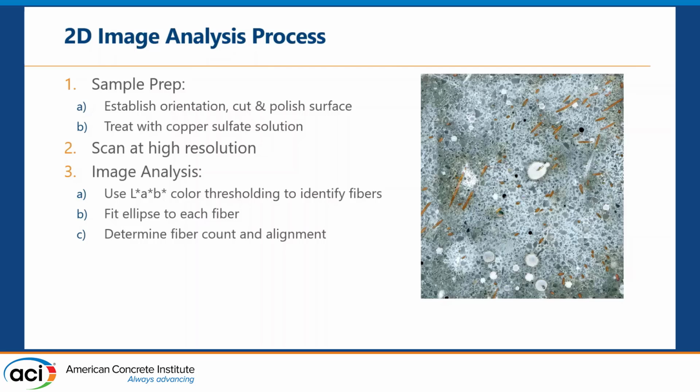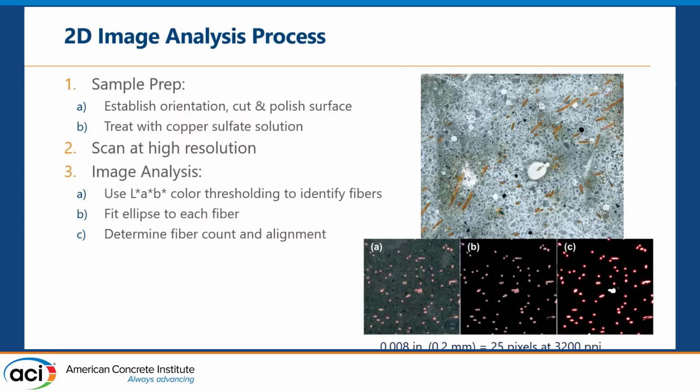We scan the surface at high resolution, and then we developed a MATLAB code that can analyze the image and can identify fibers based on the colors. We fit an ellipse on each fiber, and then we determine the fiber numbers and the fiber alignment.